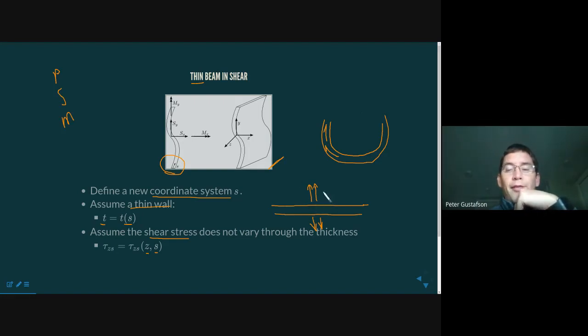So we have essentially that, in the way I'm drawing it here, sigma yy is equal to 0 on the top surface. Sigma yy is equal to 0 on the bottom surface. And so we really have no large magnitude, certainly sigma yy, anywhere through the thickness, because on the top surface it's small, on the bottom surface it's small, and there's no geometric space for there to build up any stress.